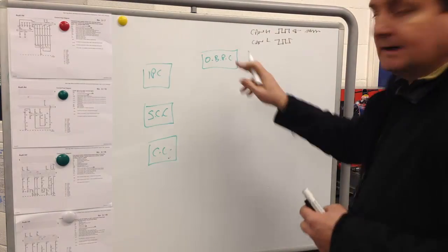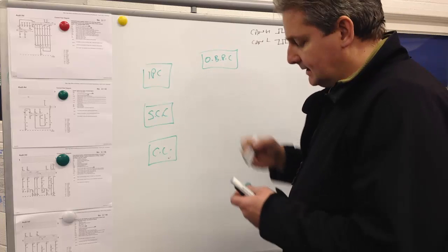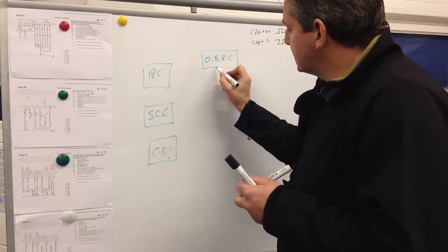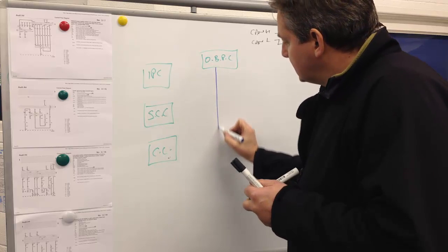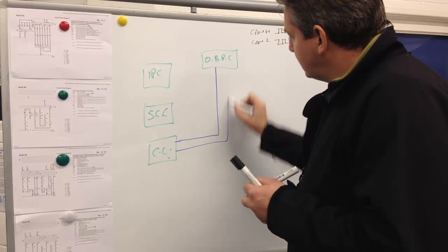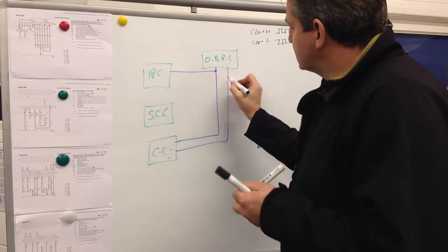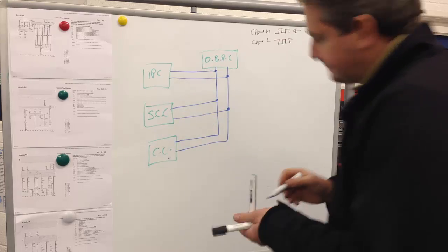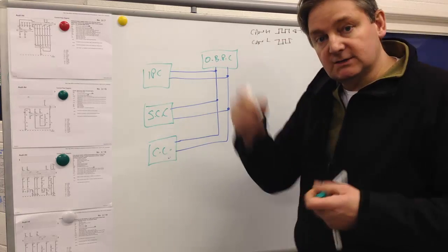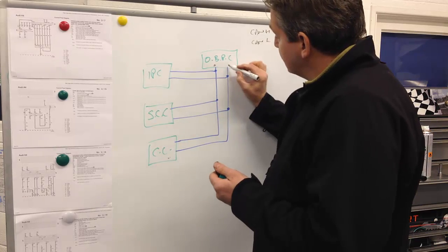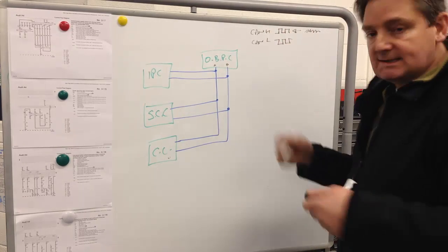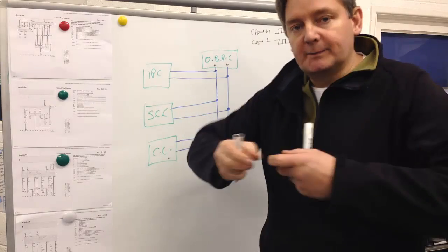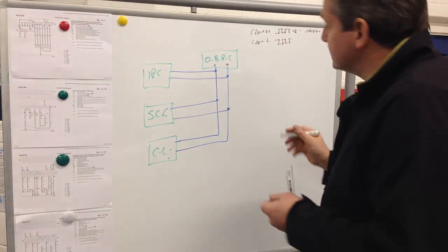When we look at our connections and the way the diagram's set up, what we're thinking is, essentially the way it looks if we draw the CAN in a slightly different colour, the onboard power supply unit is connected via two wires, which we'll call CAN high and CAN low, to my other units. So each one of them has got a connection, CAN high and CAN low, and we're taking the measurements with our scope that we've just seen at this point here, A, and at this point here, B, and we're getting our signal with it disconnected. We're getting a perfect signal, and we had to remember test it disconnected to be able to find the pins in the plug. We put it back together and plugged it in, and then we got our odd fault code.